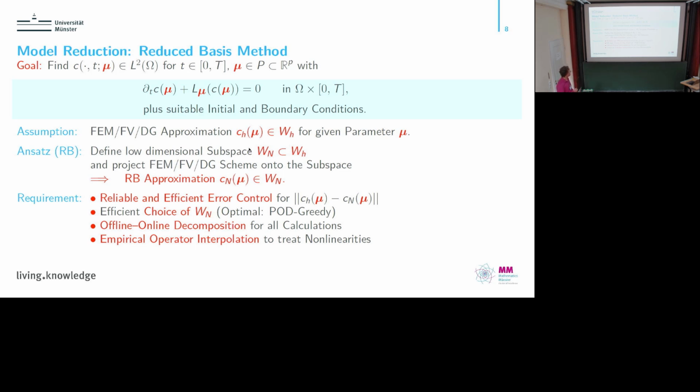And finally, for non-linear problems, this offline-online decomposition can only be done if you construct an approximation of the operators such that you can approximate in an affine decomposition, and this is, for instance, achieved by using empirical interpolation. So these are the concepts here.